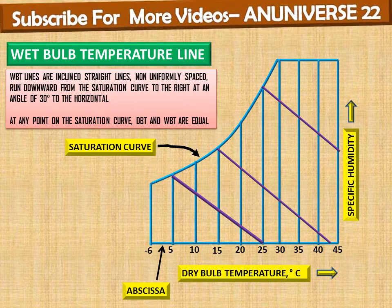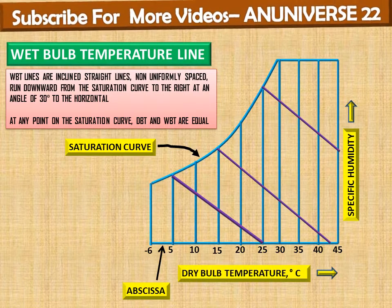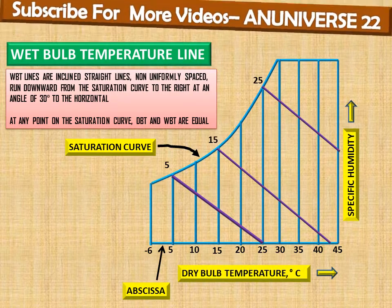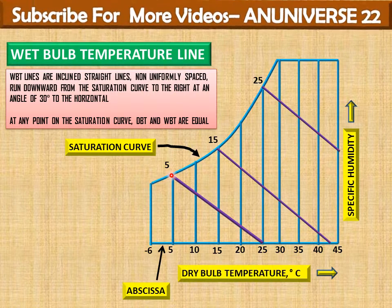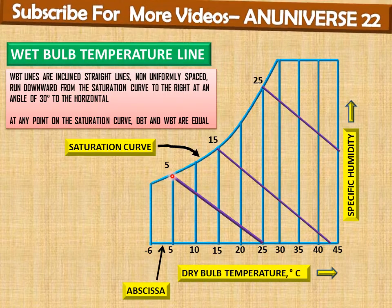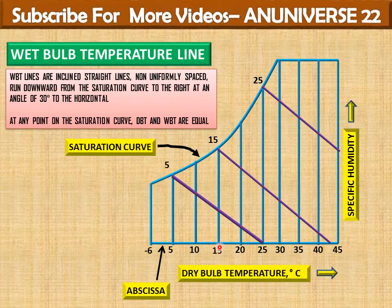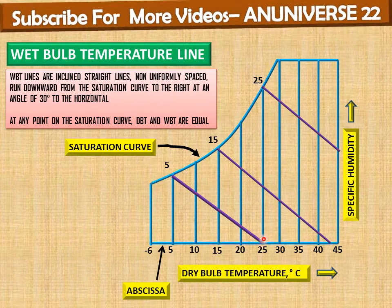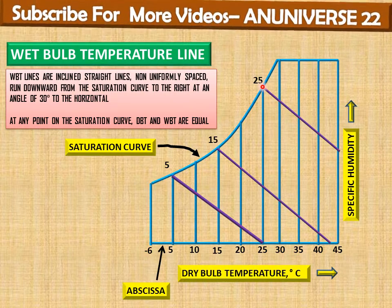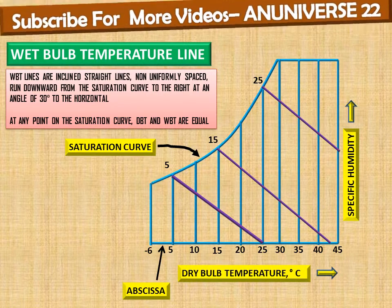At any point on the saturation curve, dry bulb temperature and wet bulb temperature are equal, as we can see here. Here the dry bulb temperature is 5 degrees and the wet bulb temperature is also 5 degrees, and at this point 15 degrees Celsius is the wet bulb temperature and 15 degrees Celsius is the dry bulb temperature, and here 25 and 25, both dry bulb and wet bulb temperature are 25 degrees Celsius. So these are some points at which both the temperatures are equal.